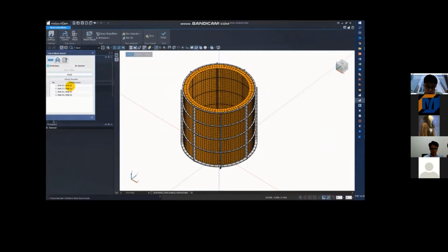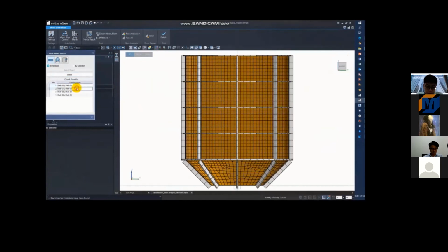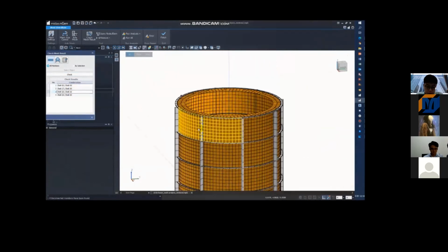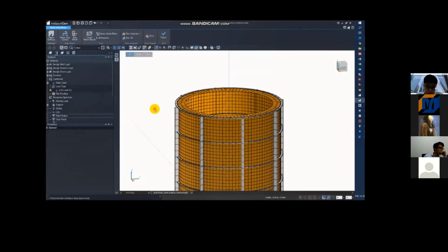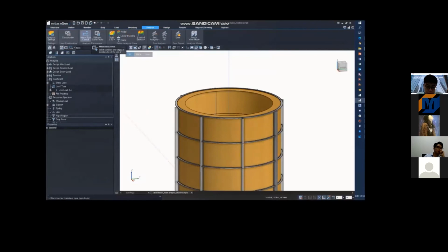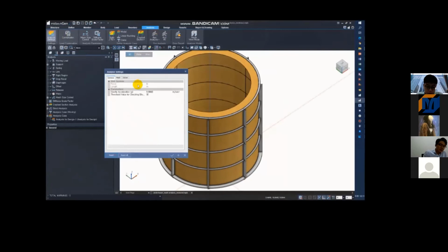To pinpoint elements with problems, execute the check mesh results. When I click the list, the program flashes elements as shown on the screen, so the location is easily detected. In a large percentage of cases, the problem is caused by modeling, so modifying the model will be the solution. After modifying the model, I can confirm that the deformation shape becomes normal.